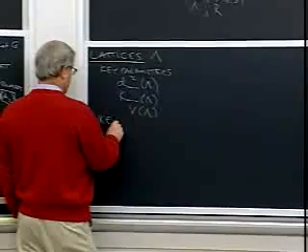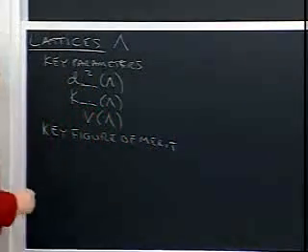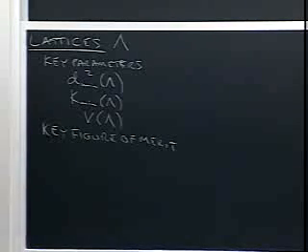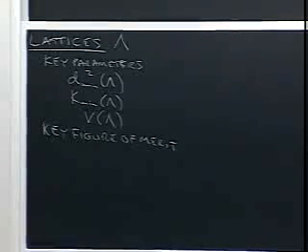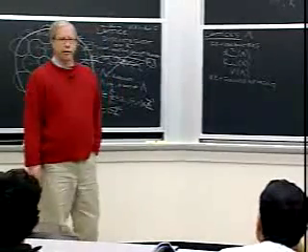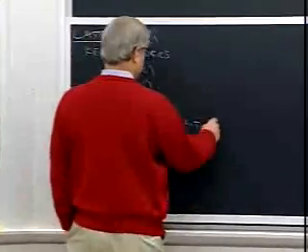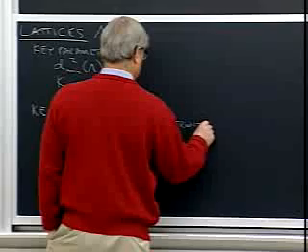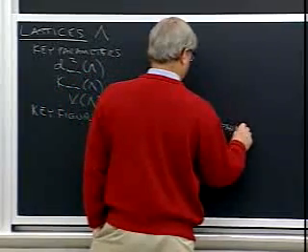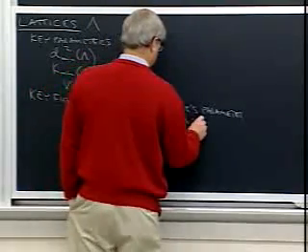So I want to combine these into a key figure of merit for coding. We did this back in chapter 4 for a complete constellation. We found a figure of merit by holding the average power fixed for a fixed number of points M and a fixed dimension N, and maximizing the minimum square distance, or conversely holding the minimum square distance fixed and minimizing the average power. So we get some figure of merit that was normalized, and we could just optimize that one thing. The key figure of merit was called by the 19th century mathematician Hermite's parameter, but we are going to call it the nominal coding gain, because that's what it's going to turn out to be.